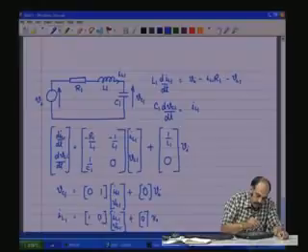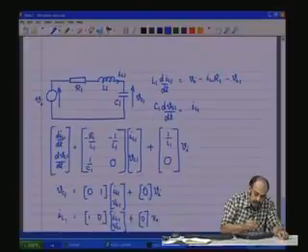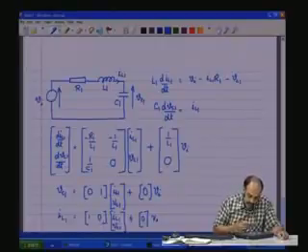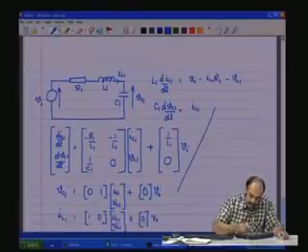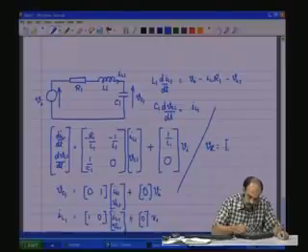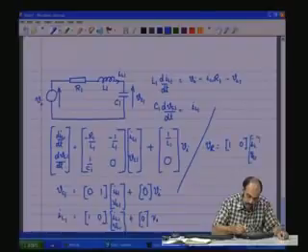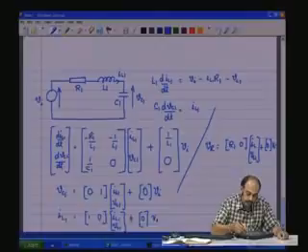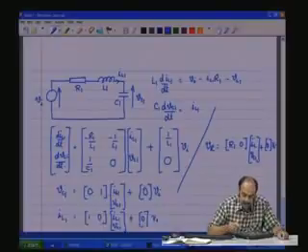the voltage across R would be the state variable IL1 passing through R1, and therefore R1 into IL1. So, if you had wanted VR, it would be 1, 0 times IL1, VC1, plus 0 VI, but this should be multiplied by R1. That would give you IL into R1, which is VR. So, you see that you could see any variable to any variable.